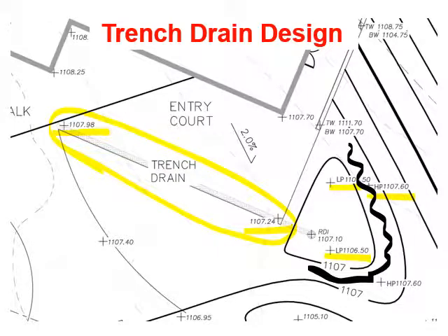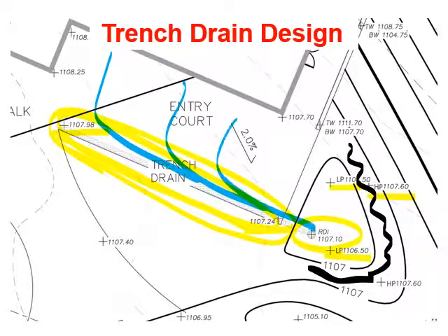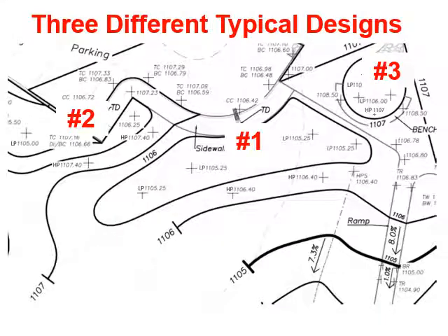And you'll need to have the elevation for the raised drop inlet. So these are the same pieces that you've seen in previous designs. The only difference is that we've added in this trench drain that then diverts water down into a smaller retention area. So now we want to talk about three typical designs that you're going to be using, three typical systems that you're probably going to need to understand how they work in order to complete this exercise.